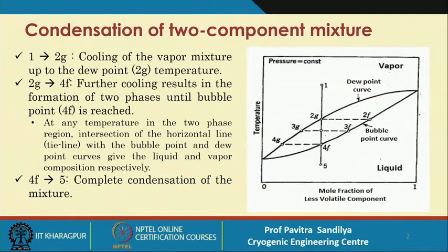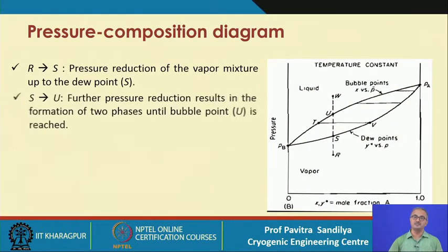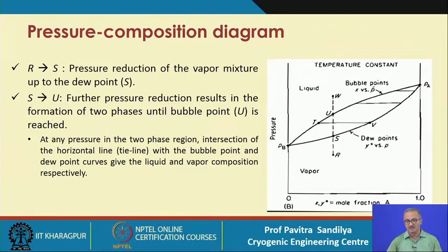Here you can see that in this case, we find that these two extremes are representing the boiling points at the given pressure, and whichever has the higher boiling point is less volatile. Okay. So, the less the volatility, the higher the boiling point; the less the volatility, the lower the vapor pressure. So, that is how we distinguish between this pressure representation and the temperature representation.